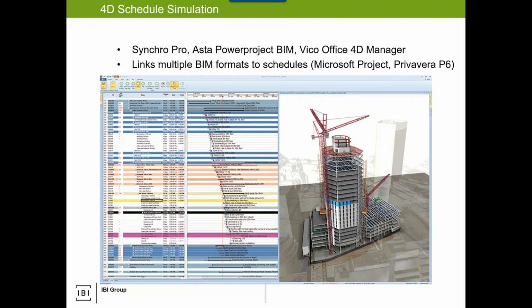Now, if it's just a traditional design-bid-build, if you know it's going to go to a contractor for these things, you can try to plan for it accordingly. But if it's design-build and the contractor wants that model and you're the BIM coordinator on the design side, take that model as it starts and get it to the contractor. Start to analyze and interpret what's being done, how it's being done, and whether it is successful in facilitating and achieving the BIM use. Don't wait until the end. Don't wait till the model's at 90% to find out there's a fundamental error that could have been fixed or set up back at 20%, for example.